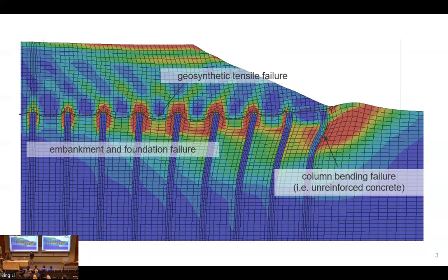And actually there is another question. This is the real situation for the foundation, I mean the real case. What do you mean by real case? I mean the placement of this pile foundation for this kind of job. Yeah, this type of system is used. Obviously, the geometry of the column arrays may differ, and the geosynthetic reinforcement at the base is another optional feature, but people tend to place one or two layers of geosynthetic reinforcement to resist lateral spreading. Or at least that's the intent.